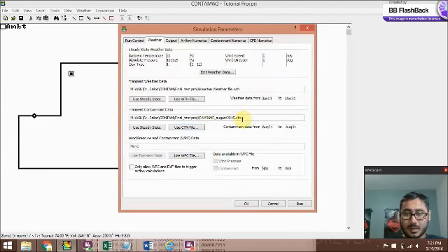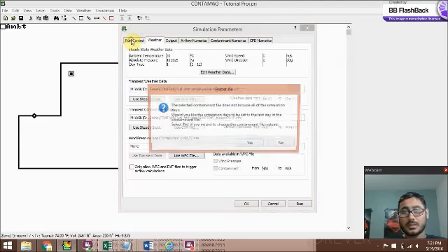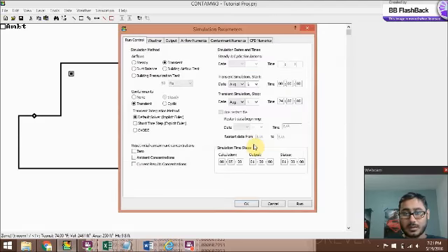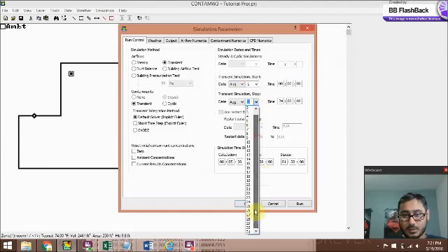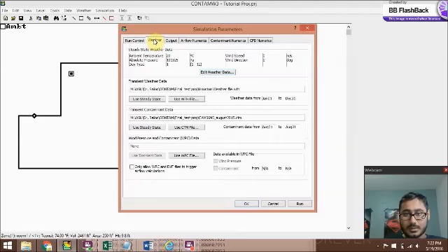and once those are imported, this would give you your data from where the weather file is and what the contaminant is. So make sure your contaminant data is within your weather file. If these both mismatch, you will not be able to simulate the data. So let's set August 1 to August 30. That's what my contaminant data is, August 1 to August 31st.